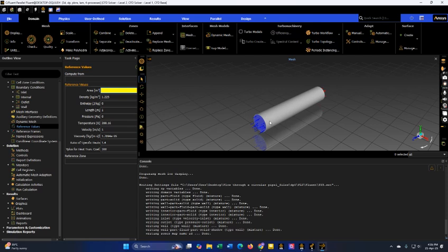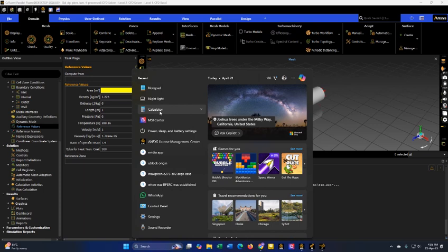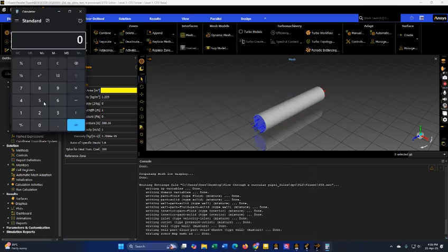So I have calculated the area for this pipe. If the radius is 0.075 or 0.073 actually, but let me show you how I do it. Let's choose the calculator, and the area for a circular pipe is pi r square, simply that. So 3.1416 into r square. R here is just 0.073, the inlet one, so 0.073 square. 0.5329.